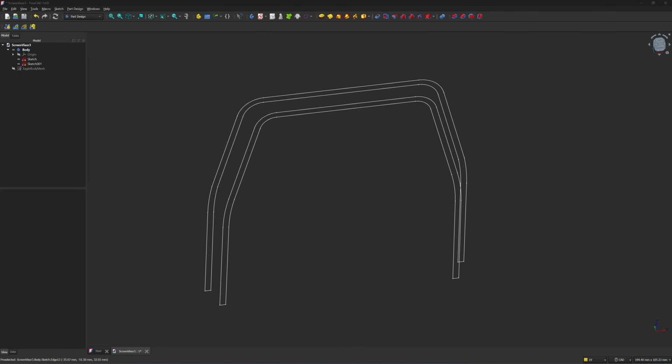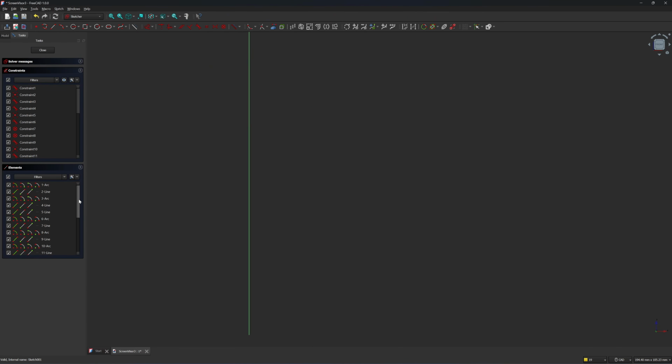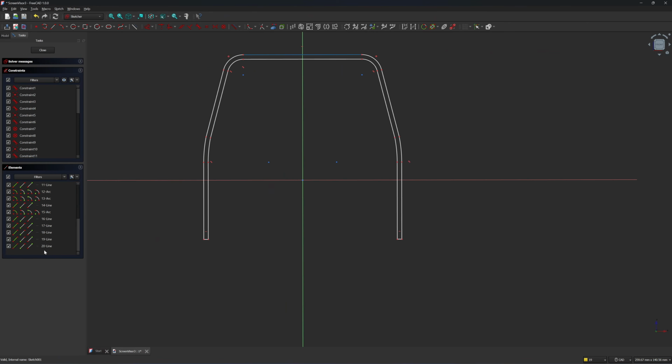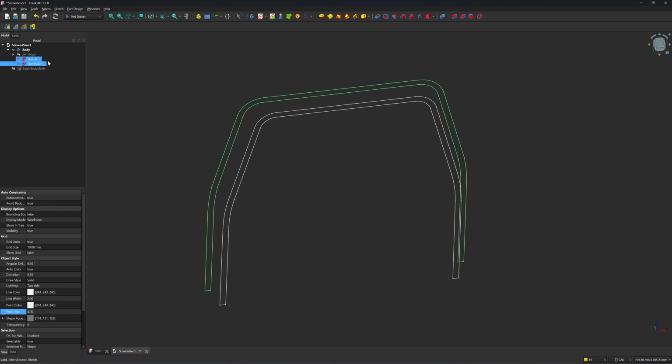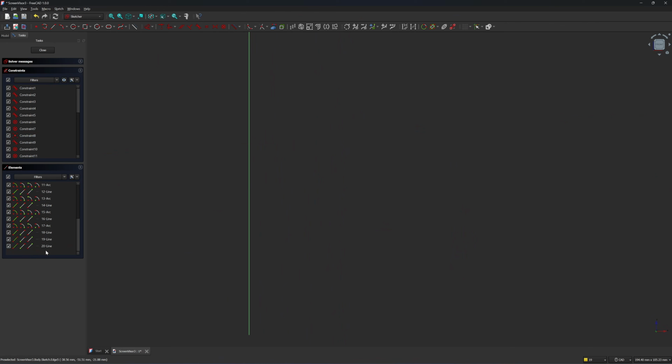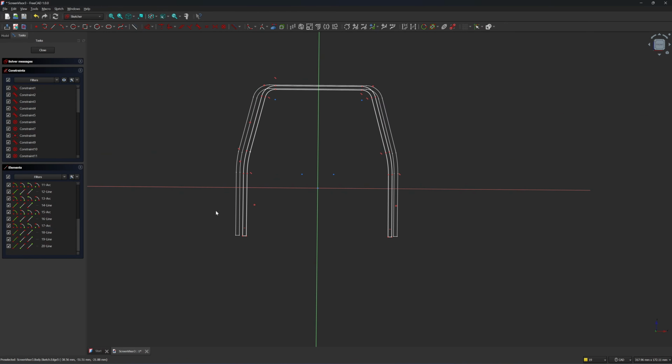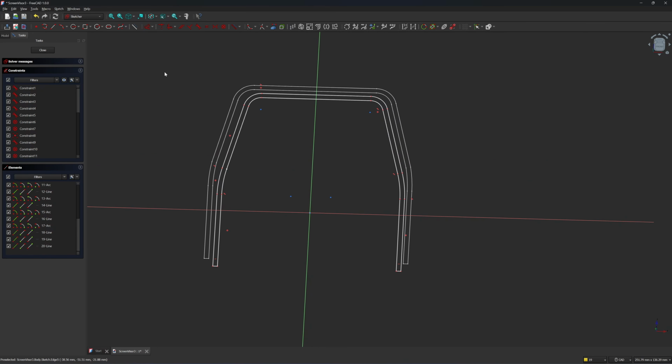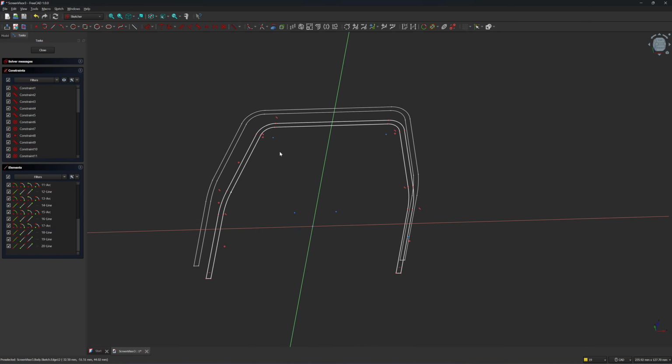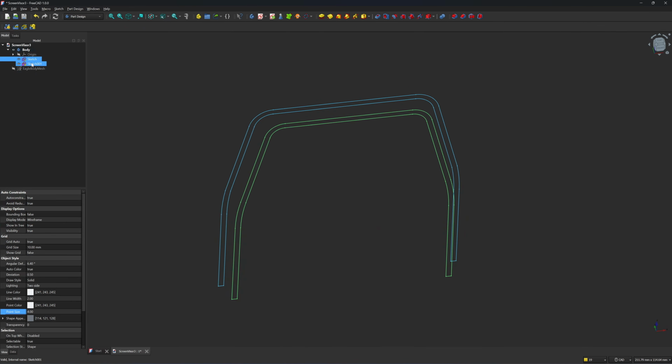One easy way to check, you're going to go to the sketch and see here, this sketch contains 20 lines, right? So your second sketch has to contain 20 lines. If your second sketch and first sketch have different numbers of lines, it will not be able to loft. So please keep that in mind. Each line can have different radius, different length, different orientation, but it needs to have the same amount of lines to create a loft. So this time it will work, I can guarantee.